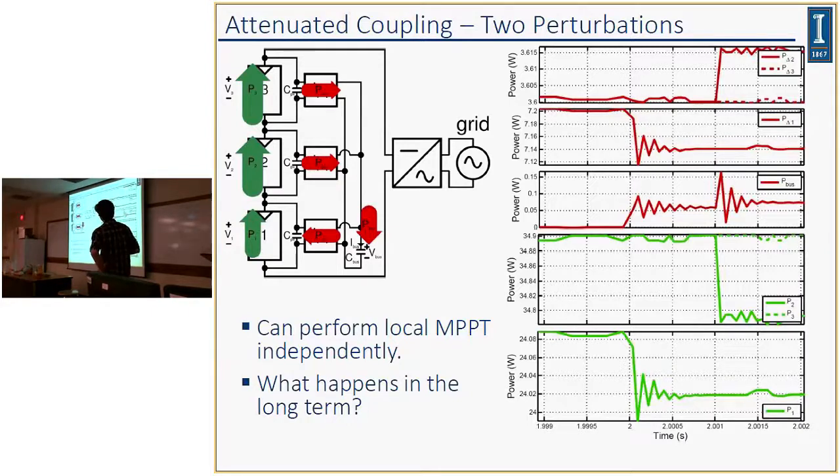So you can perform a maximum power point tracking algorithm locally and irrespective of each other, such that if converter 1 perturbs its state, it doesn't affect the other submodules, and it knows that if it perturbed in one direction, it decreased the amount of power that its corresponding submodule was producing. So it knows that it needs to step in the opposite direction on its next perturbation iteration.